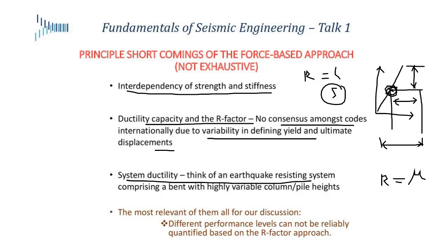And the most relevant is that I cannot, with any reliability, define different performance levels or quantify different performance levels. I cannot tell my client or my fellow engineer how my bridge is going to be behaving and what it is going to look like at the end of the earthquake. What is its performance going to be? Am I going to be able to put some emergency traffic on it? Am I going to be able to put all kinds of trucks on it? Am I going to have to completely shut it down? It's very difficult using the force-based design to do that.